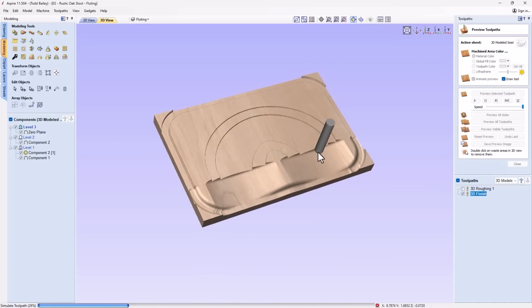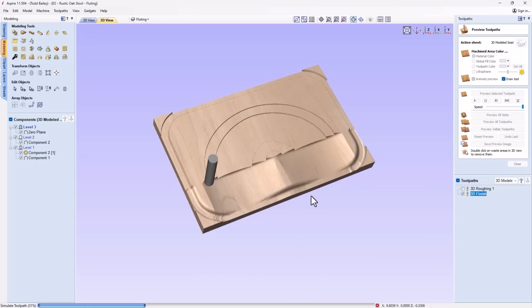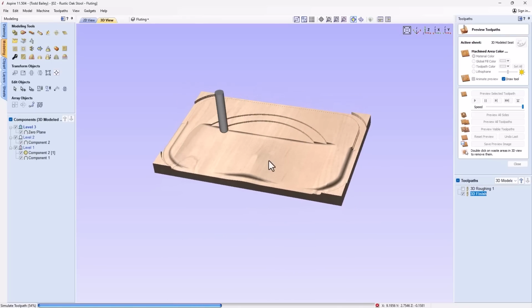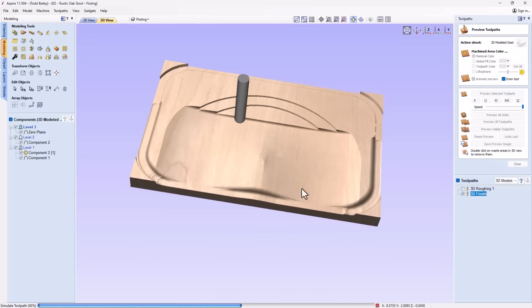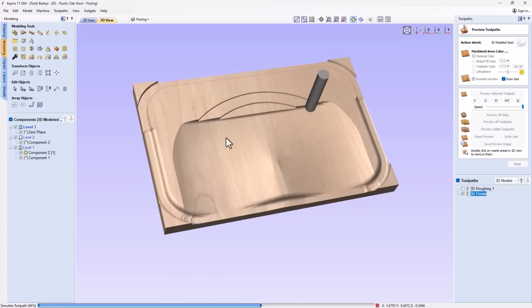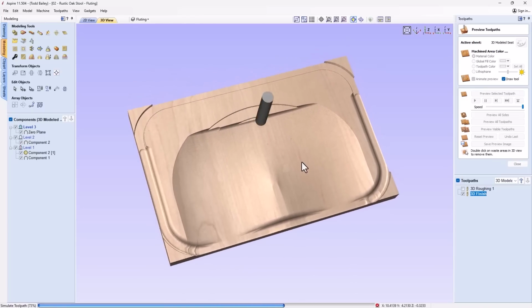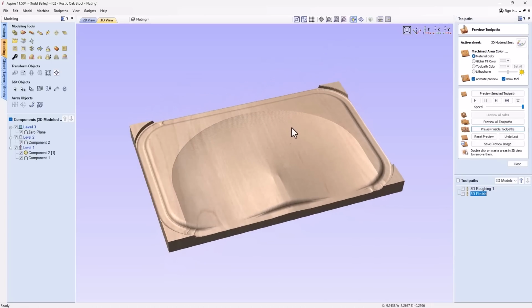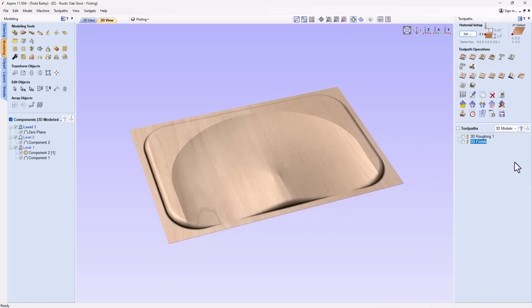One of the problems that I see here is that as that seat recess or impression rounds up to the edge of my seat, there's quite a heavy, sharp line. I think what I would do in the end is go back in and adjust that profile vector that I did the 2-rail sweep with, and make it a little rounder on the top. And I think I'll do that with the file that I'm going to give you. And that looks really nice in the end. There's that spot right there I'm going to fix. And we can go ahead now and jump right into our cutout pass.